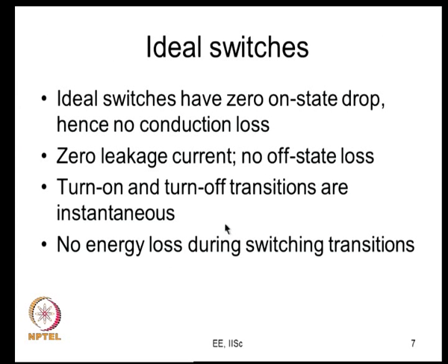So, first we have to see what this dead time is. It is actually some time interval between the switching of the top and the bottom devices. So, actually you have to get back to what switches are, or why they are. These are the ideal switches we have seen a number of times. We have discussed this idea earlier, particularly when we were discussing the losses. An ideal switch is supposed to have no forward drop and no conduction loss. It has no leakage current and no off state loss, and the turn on and turn off transitions are instantaneous, with no energy loss during switching transitions.